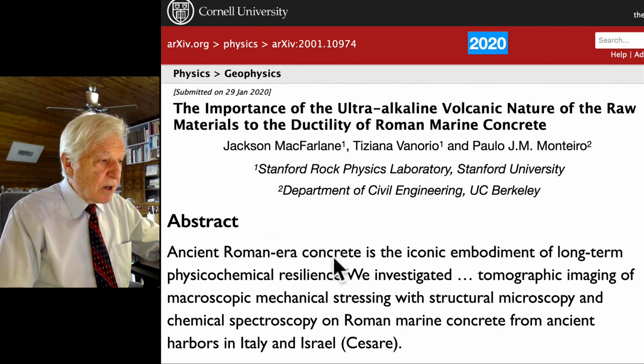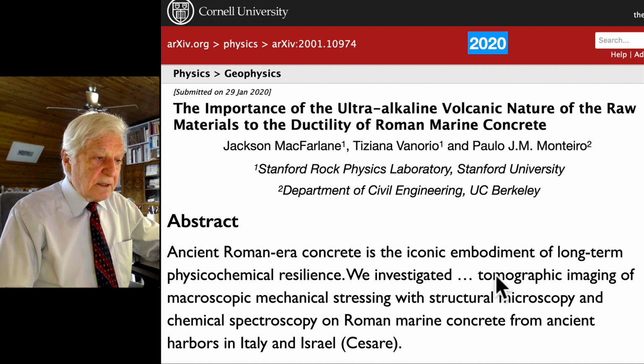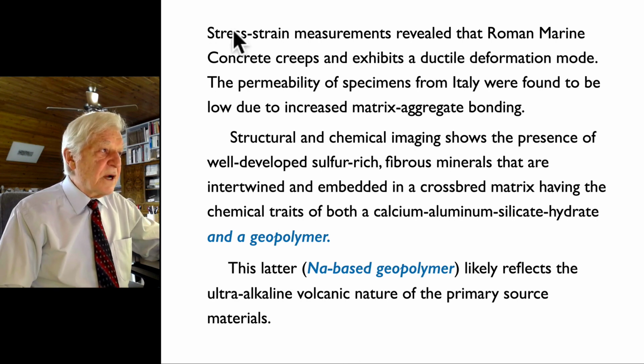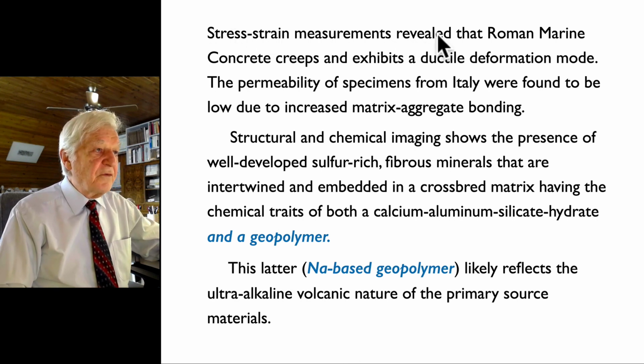Ancient Roman-era concrete is the iconic embodiment of long-term physico-chemical resilience. We investigated tomographic imaging of macroscopic mechanical stressing with structural microscopy and chemical spectroscopy on Roman marine concrete from ancient harbors in Italy and the one in Israel that is called Caesarea. Stress-strain measurements revealed that Roman marine concrete creeps and exhibits a ductile deformation mode.